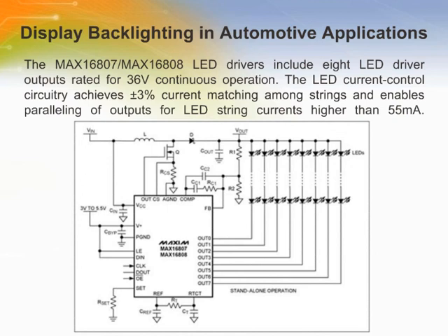Today, more and more liquid crystal displays, LCDs, are used to display information in instrument clusters, car computers, radio and navigation systems, and entertainment systems. Moreover, display backlighting diffuses light across a large area instead of generating a focused light beam. LCD backlighting is to use a matrix of LEDs, providing homogeneous illumination and color over the full area.